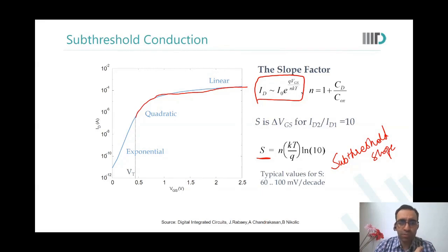It could be both. Over here, we're talking about subthreshold current, which means charge flow from source to drain. But in reality, leakage will happen everywhere. Because this slide is on subthreshold conduction, over here we are talking about charge that would flow from source to the drain. Okay, sir. Understood. I know that there is a depletion region, a PN junction on the source. There is also a PN junction on the drain, and there is a depletion region in between them.